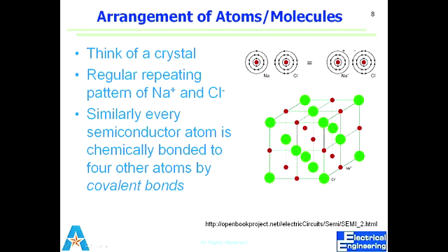So this is a simple idea: there is a repetition of atoms. There's repetition, so the structure has a long-term order to it, right? Long-range order is the keyword. Sodium chloride crystals are not long-range, so you have small grains. There is a structure, but it is confined to a very small area. What we want in a semiconductor is long-range order, what we call a single crystalline structure. There's no break in that structure. It's also called a lattice.